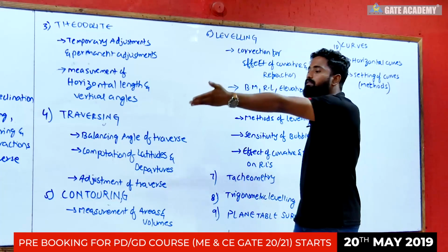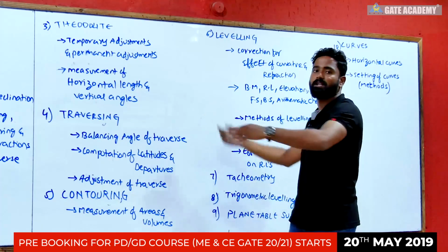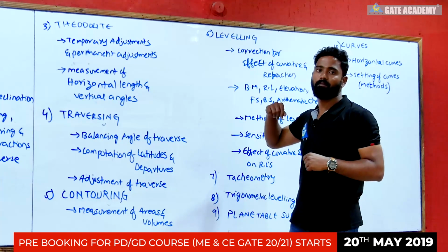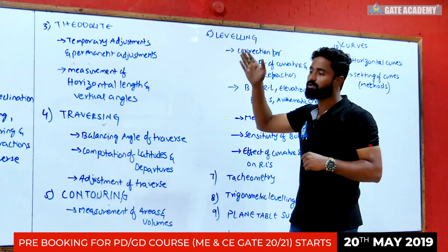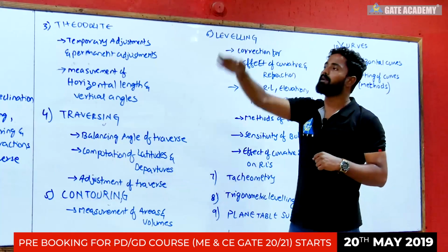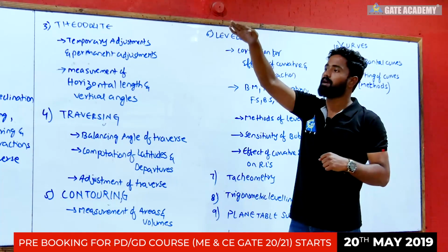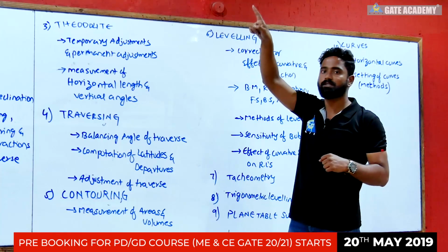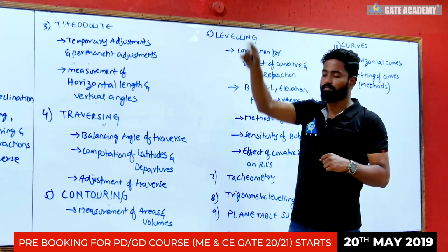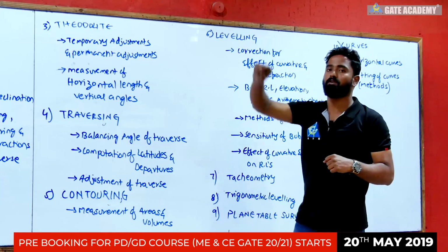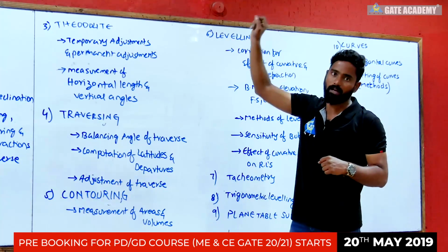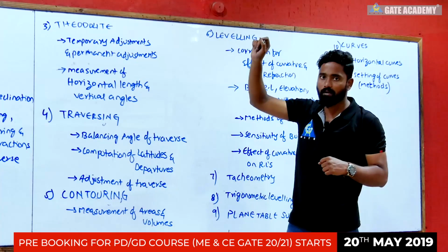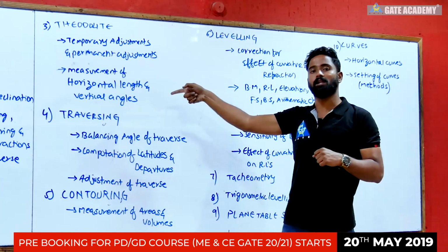I know the elevation of that point is 150 meters with respect to the mean sea level. So, with respect to this one, I will measure the elevation of the top level, or I will measure the elevation of this beam. From here to here, or this slab, I will measure the distance. So, finally, I will get the reduced level with respect to the mean sea level.